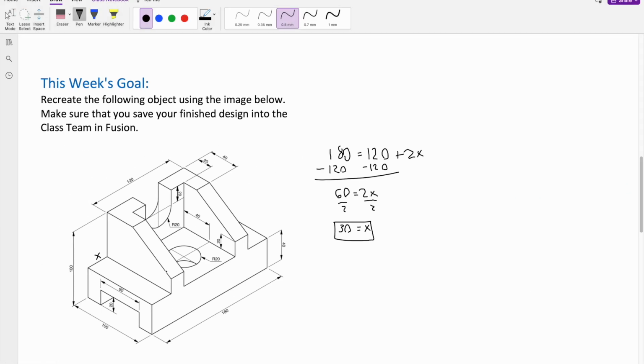We're still missing some key features, like we're missing this little U back here, we're missing these two slants, and this little cutout down here. So what we're going to do is we're going to actually create two additional sketches on the surface that we already created, and then just extrude away the parts that we don't need.